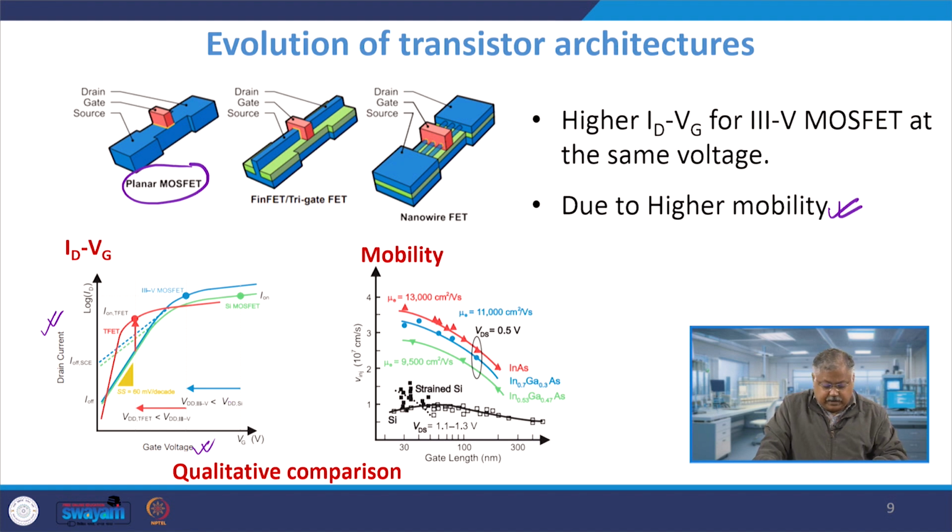the red colored one which you see is for TFETs, basically tunnel field effect transistor, whose subthreshold slopes are relatively very low, and it is even smaller than 60 millivolt per decade, very good switch. However, its on currents are relatively small, as you can see, it's tapering out as it goes to high values of ID. If you look at the green one, which is silicon MOSFET, then its on currents are also relatively